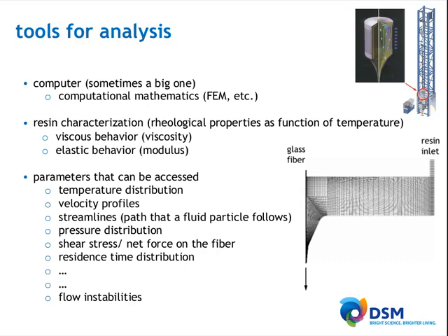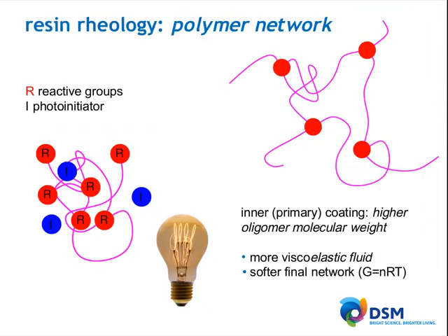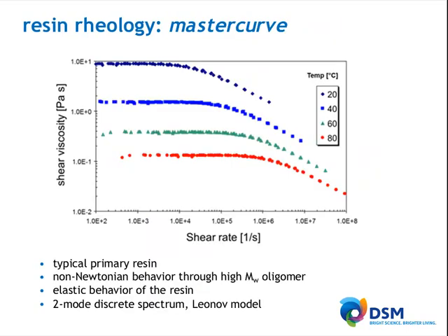incidence. And you can imagine that typically the primary coating, which has a low modulus, a low cross-link density, has a relatively high molecular weight oligomer structure. Typically, high molecular weight molecules relate to elastic effects because they simply stretch further and easier than the shorter molecules, which tend to behave more Newtonian. I actually see that back if you look at one of the things that we put in the model.